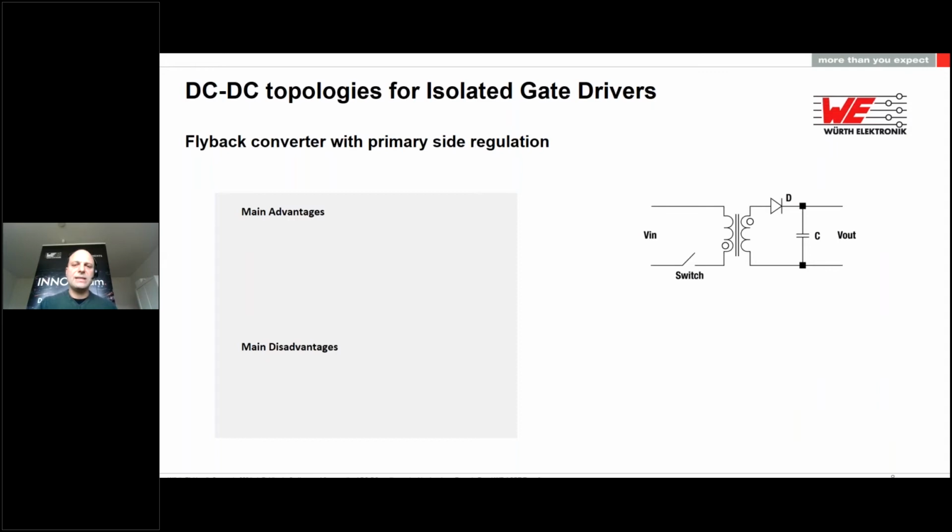The flyback is essentially a buck-boost topology that is isolated by using a transformer as a storage inductor. The transformer not only provides the isolation, but by varying the turns ratio, the duty cycle can be balanced and optimized for the output voltage. The flyback is the simplest and the most common of the isolated topologies for low power applications.